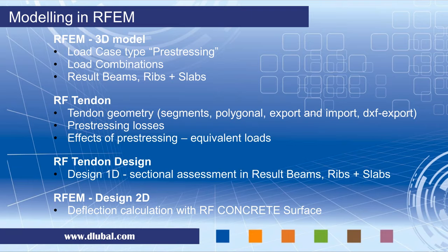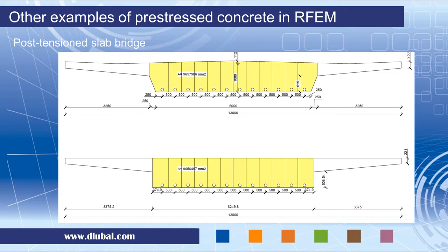Now you have one load case, like for example self-weight, which acts downwards, and of course pre-stressing acts upwards, and you can perform the analysis of 2D members, I mean a 3D structure with the slabs, and you can also perform 2D design directly in RFEM. And after you have this potential additional reinforcement, additional to the one which we found in result beams, you can also perform non-linear analysis of 2D structures, of 2D slabs. We definitely will show it during the seminars.